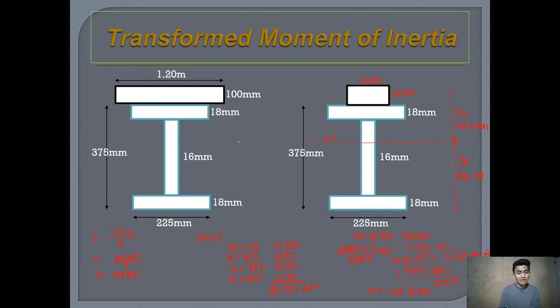So instead of considering again three sections, so that I can eliminate AD squared at the end of our equation for a moment of inertia, I will consider the whole rectangular figure.